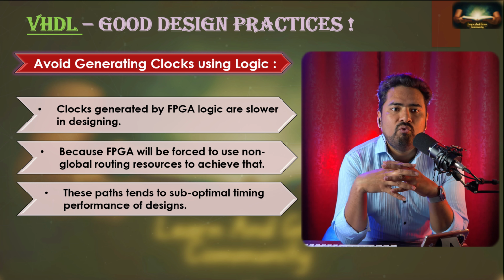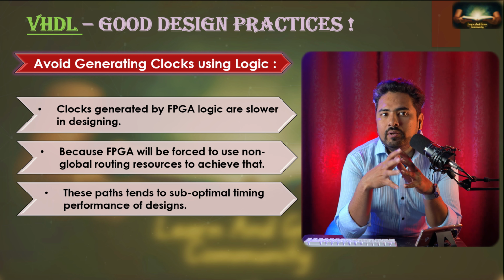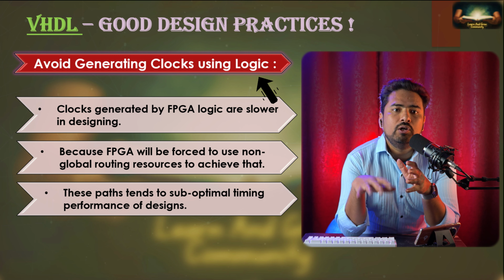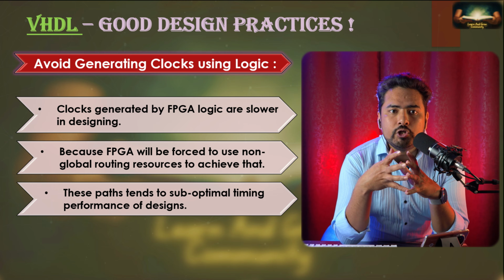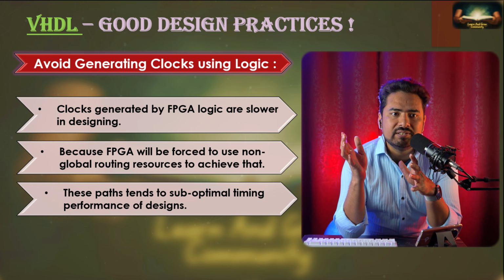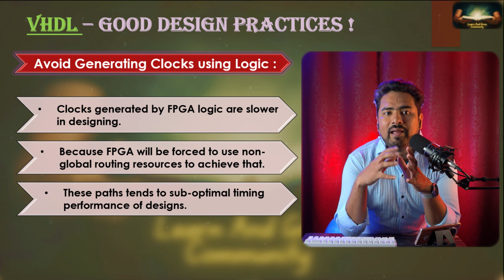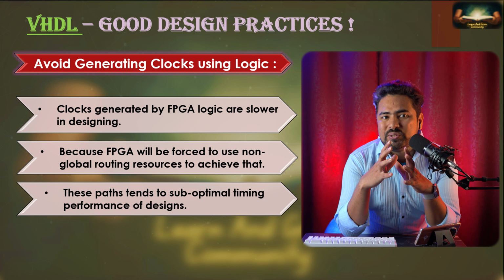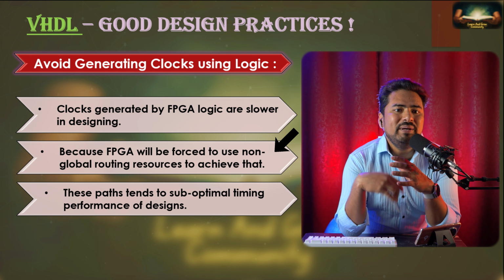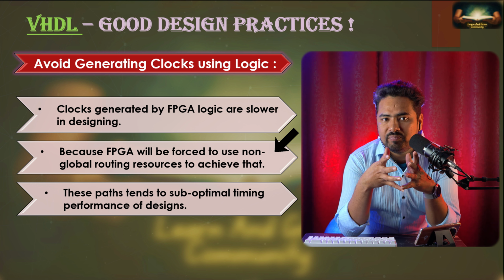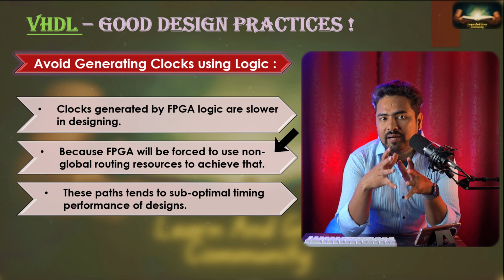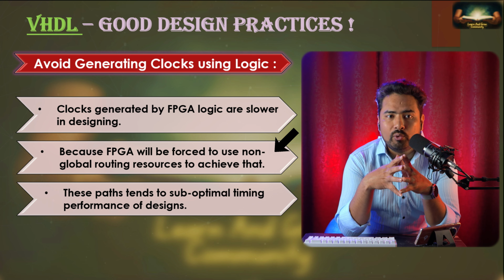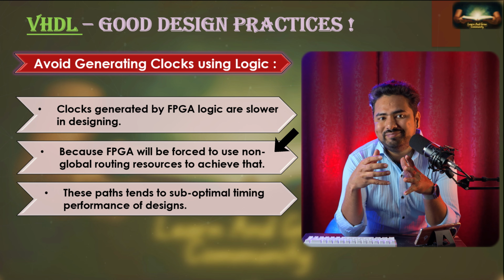Now understand what the problems are when you generate your clocks using logical elements like we did. Your FPGA can have multiple regions from where it can get an external clock signal. So your routing or placement of elements can create problems. The delay of your clock signal can also vary depending on where that flip-flop is located inside the FPGA.